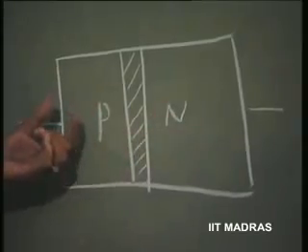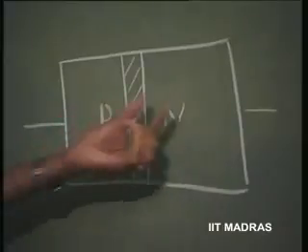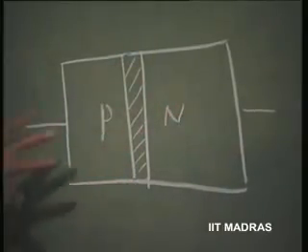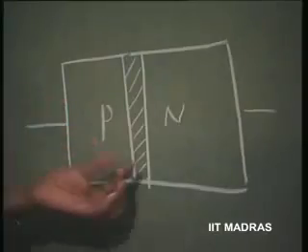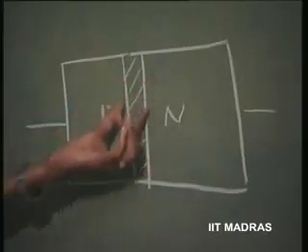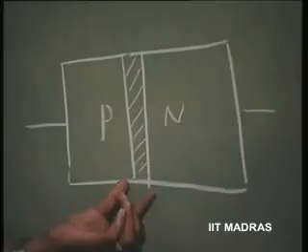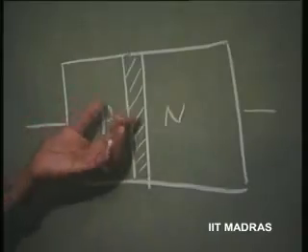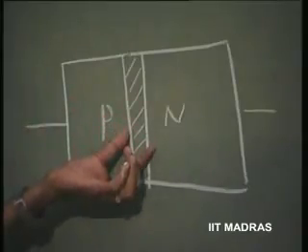Even though for the holes here as well as the electrons here there has been a barrier potential hill corresponding to 0.5 to 0.7 I said, because of the existence of the depletion layer. This is happening the moment I formulate the junction. For us to have an equilibrium here, there is a potential hill created.